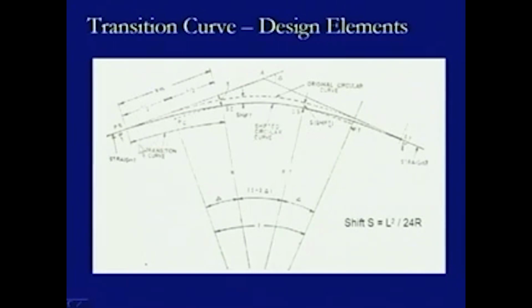And this will be the length of the transition curve, this is the total length, and this is the tangent. So, we are getting this tangent starting from the straight section. If we draw it like this, then there will be an angle alpha at this point if we draw another tangent. And in this case, this shift which we are taking here, if we continue this circular curve which is being displaced in this direction, then it will be coming to this location.